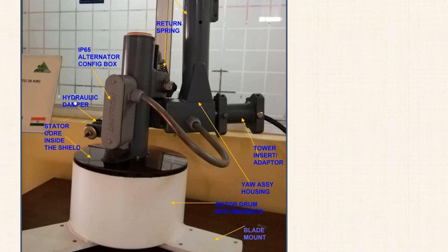because of the tail vane, the turbine can move 360 degrees to face the maximum wind direction. So what this can do is, the cable can get tangled because of that. So this return spring ensures that the cable is not tangled in case it moves multiple times in multiple directions, maximum wind directions. Next page, please.